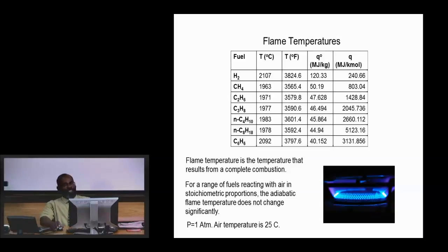So what's the discrepancy? Why are these significantly hotter than what we're finding in the upper layer? Well, if the flame is an interface, so this is the flame, and in these cases the flame is a turbulent flame, it's moving like this. It's being distorted. If you're making your measurement of temperature at any location, what are you really measuring? You're measuring all sorts of different things around the flame temperature, and you're not necessarily measuring the flame temperature.